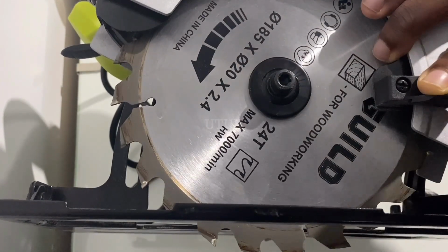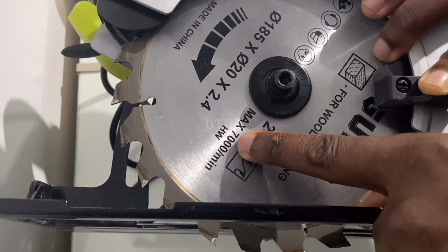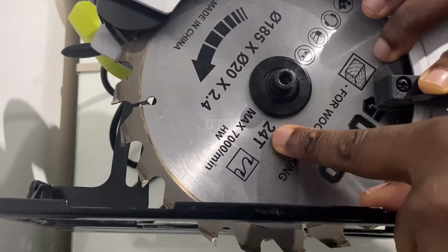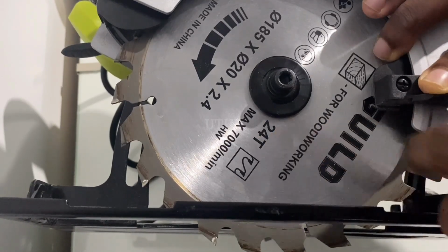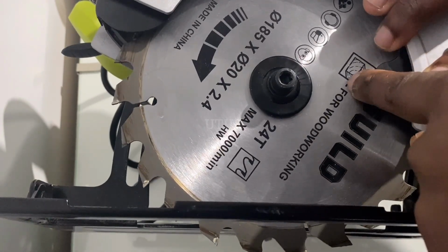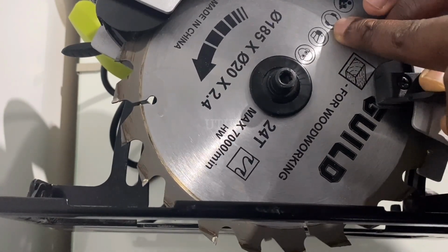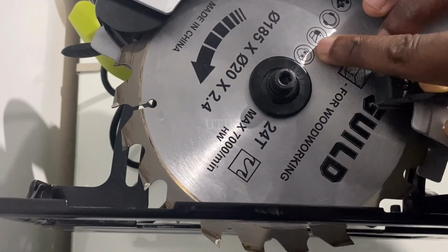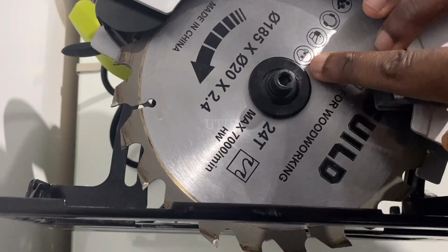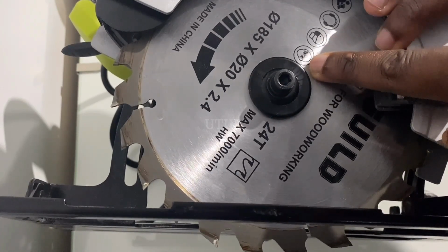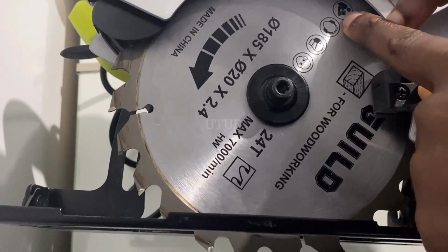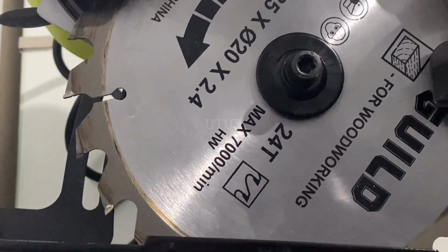This blade has got 24 teeth. And it's got large gullet sizes between the teeth, which means that it can be used to move out big chunks of wood. 24 teeth typically connotes a ripping blade, and you can see on the blade, it's highlighted that this blade is designated for cutting wood. You also have to wear your ear protection or muffs, your face mask, eye protection or safety glasses. Just pretty much take health and safety precautions, and ensure that you read the instruction manual.